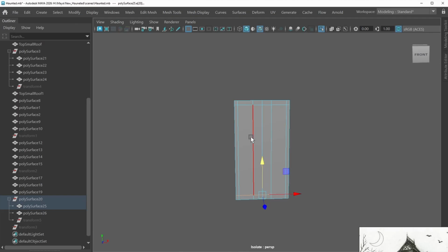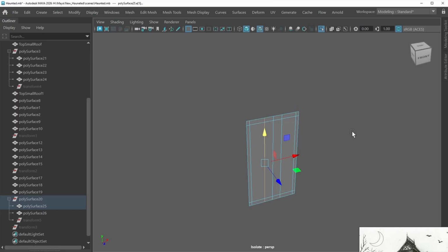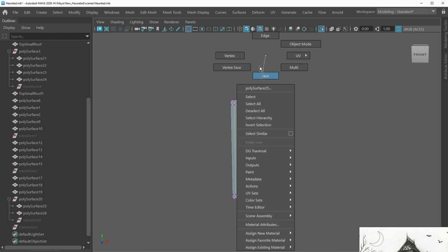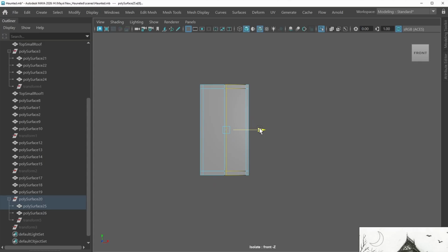And then probably I can delete this line here. And of course, when you delete a line, we have to delete these vertices. That's the thing, if you don't do that, your texturing will have trouble and come up wonky here. So I'm going to go to front here. You can see these are yellow, so hit B, basically soft selection there.